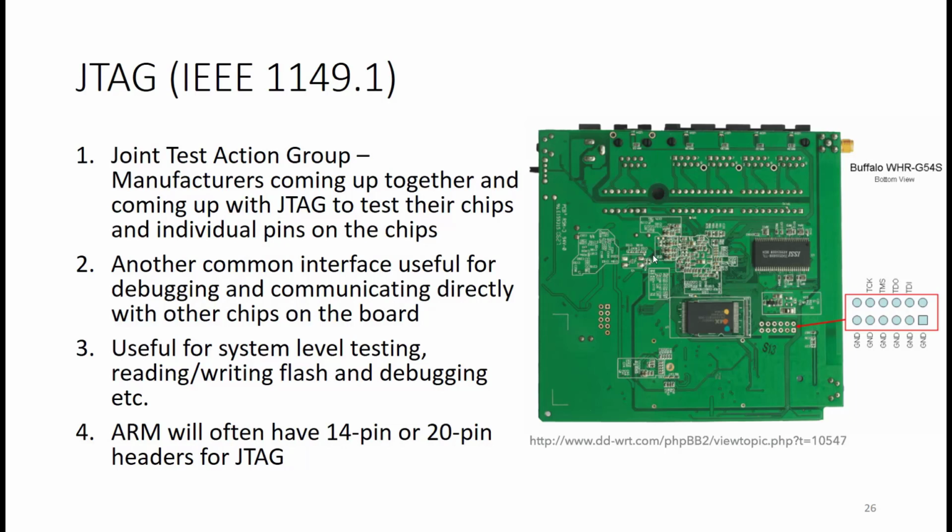This protocol is used when one component needs to interact with more than one component available on the board. As an example, let's say the microcontroller unit needs to interact with flash ROM, then communicate through Wi-Fi, and also needs to get data from the sensors of the board. In that place, instead of UART, you might find a JTAG connection.